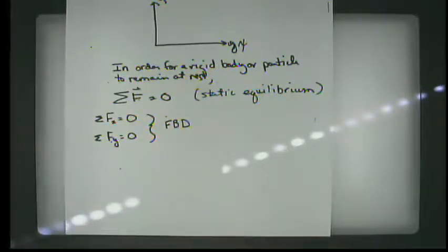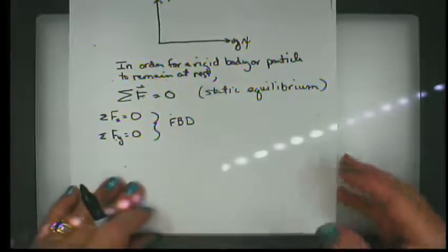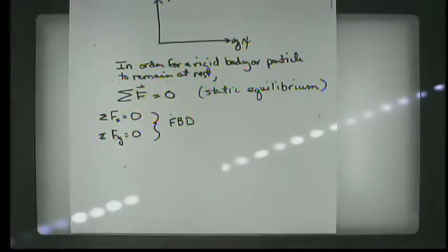So in general, a free body diagram, I like to tell people, is sort of like a very narcissistic view of the world, where there's one item that is the center of the world and everything else is acting on that center. So if we have an object, a box or a pulley or a weight, we consider that to be the center of the universe, and everything else that's acting on it is a force acting on that particular body.